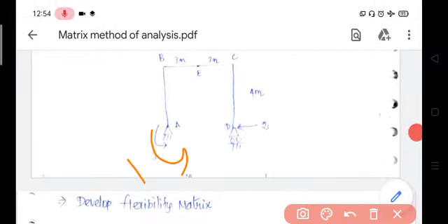It is a rotational, moment coordinate. Then at the pin end we remove Hd. Before, it was a pin support; after removal of the horizontal reaction it becomes a roller support. Now assign coordinate 2 for that horizontal reaction.